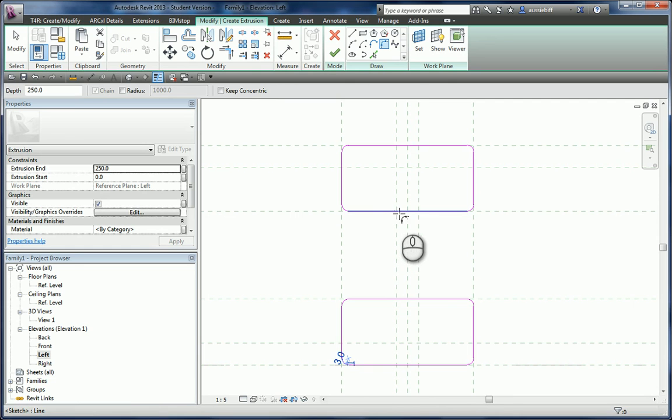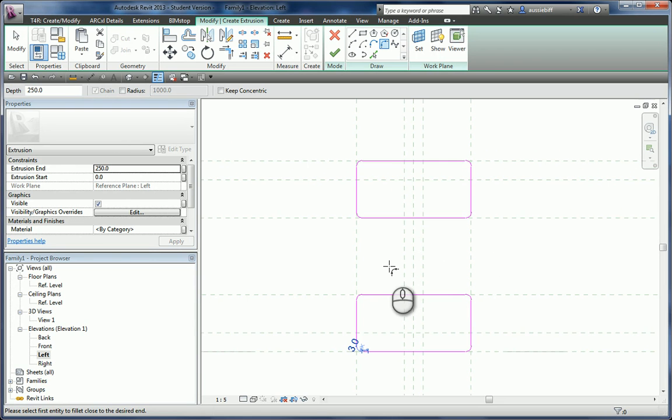Now, since the web extrudes up and into the flange, we have to cut a hole in the flange, but first off we have to work out how thick that flange is. By my guesstimations and a bit of calculations I worked out, I'll just open up the other family here and see. Oh, well, first off let's constrain all this. So if we go to align, you'll find that we can align to the reference plane, and that's the important thing, the lock.